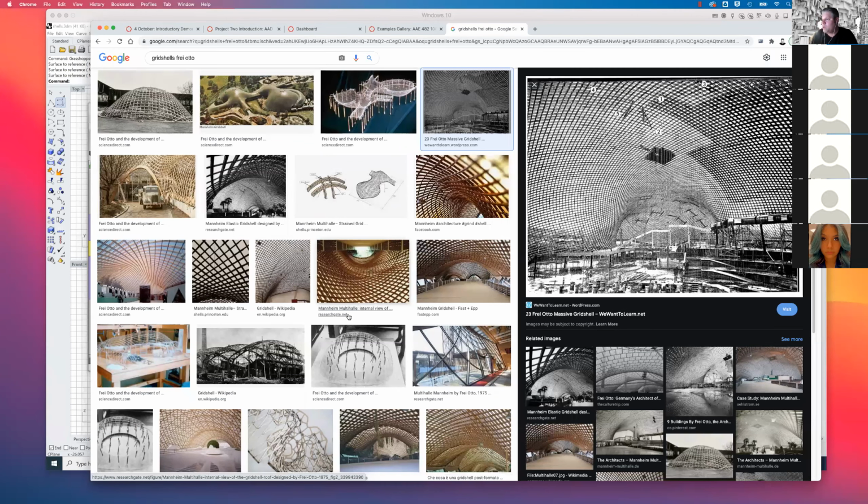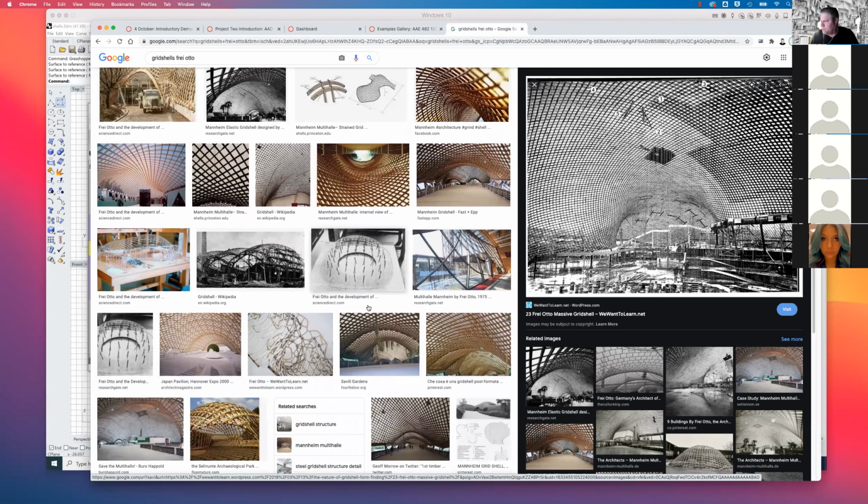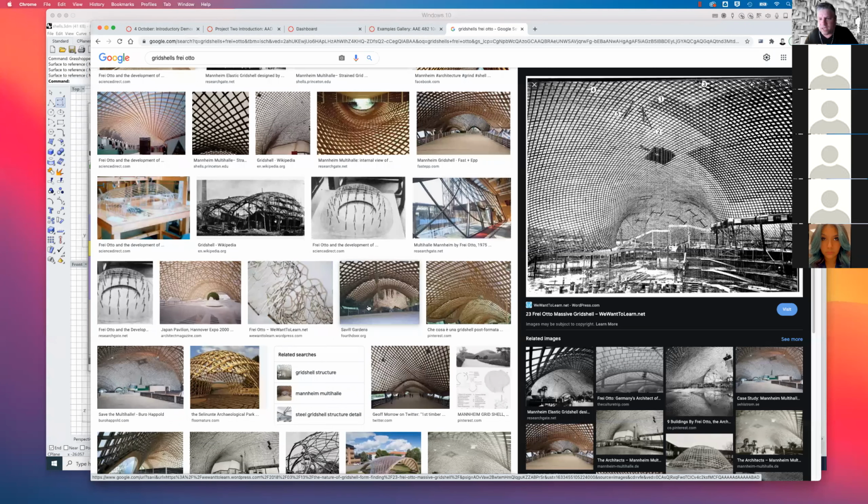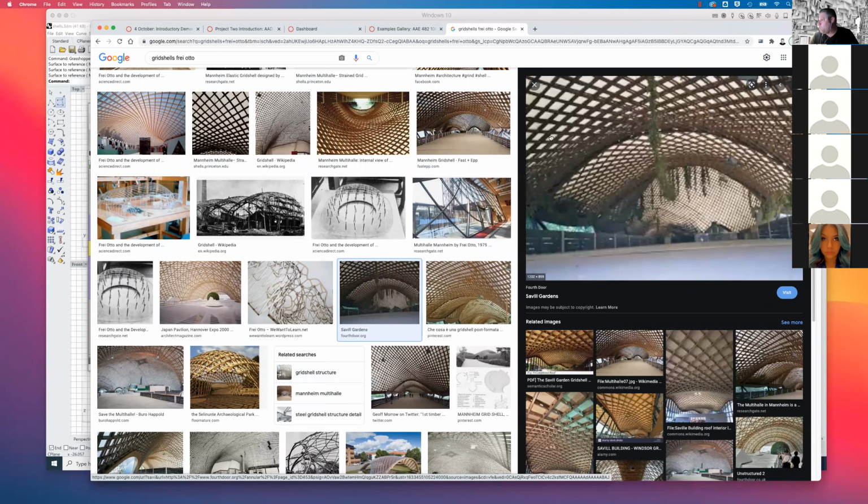And so oftentimes what you'll find is that grid shells and shell structure geometry in general are an interesting thing. You can start to model much more complicated dome-like or doubly curved surfaces with them, and they perform in really interesting ways. There's a structural redundancy. What I mean by that is if I took out exactly one of these ribs, the whole thing wouldn't just crash and burn and explode. It wouldn't just fail. There's a redundancy to this, so that you could begin to remove one or two structural members, and the system could still redistribute structural loads across the system in multiple directions.